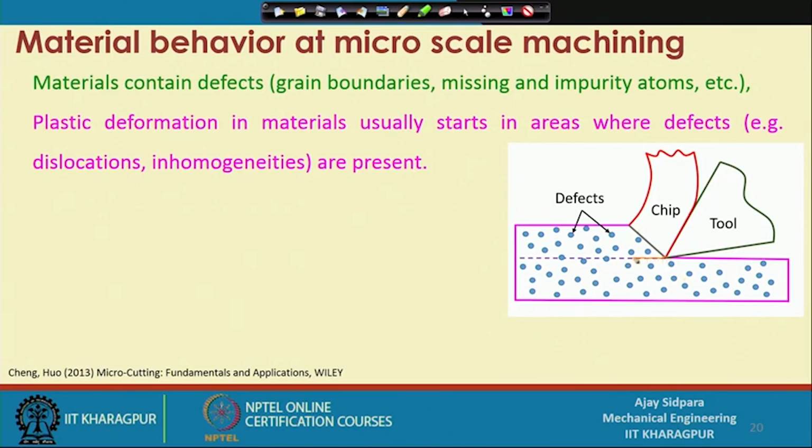If you continue in this direction, you are not encountering any defects till now, and then suddenly you get 1 defect, 2 defects, 3 defects, depending on the property of the defect, whether it is an inclusion or porosity or something other than that. Depending on that, the forces or the load on the tool will fluctuate, and when you are passing through this, you get a different magnitude of force on the tool, and that will decide the tool life and the efficiency of the machining operation.